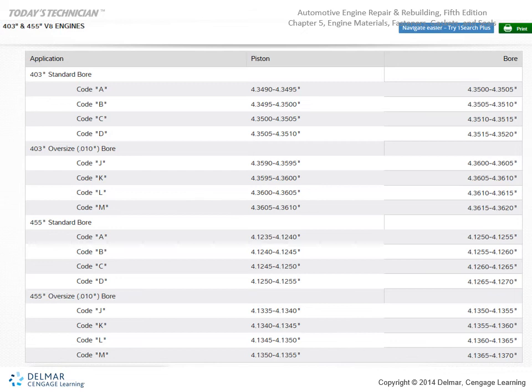So when we have a 10 thousandths and a 10 thousandths bore, we can only clean up a 10 thousandths over bored out. We can only clean up a minimal amount of damage that's in the cylinder bore. So we have some guidance here showing us that they have a 10 thousandths oversize shown here, and you're going to have a range. So the range here is only 5/10 thousandths of an inch, which is a very minimal amount of wear.